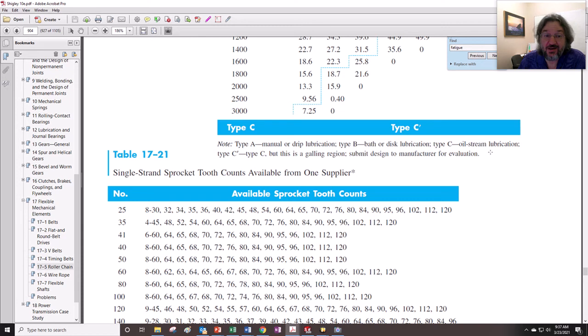Or it could need an oil stream, so on a lube oil system there might be a small takeoff with a little nozzle putting oil onto the chain all the time. They could have different setups depending on the machine, the complexity, and the importance.